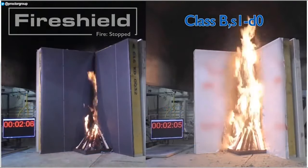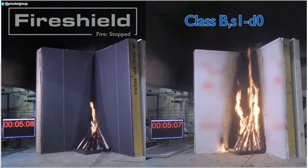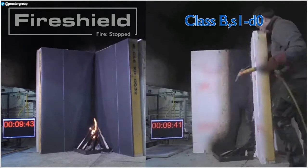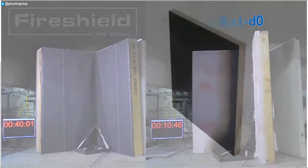As can be seen here in this comparative test, the Class B membrane on the right shrinks away and does not contribute to the fire's development. However, the fire shield on the left remains in place, with its coating protecting the substrate from ignition. This test was conducted by the University of Edinburgh and is based on the EN 13823 Single Burning Item Test. It was conducted as part of the process for inclusion in the Structural Timber Association product papers for their FR build specification.